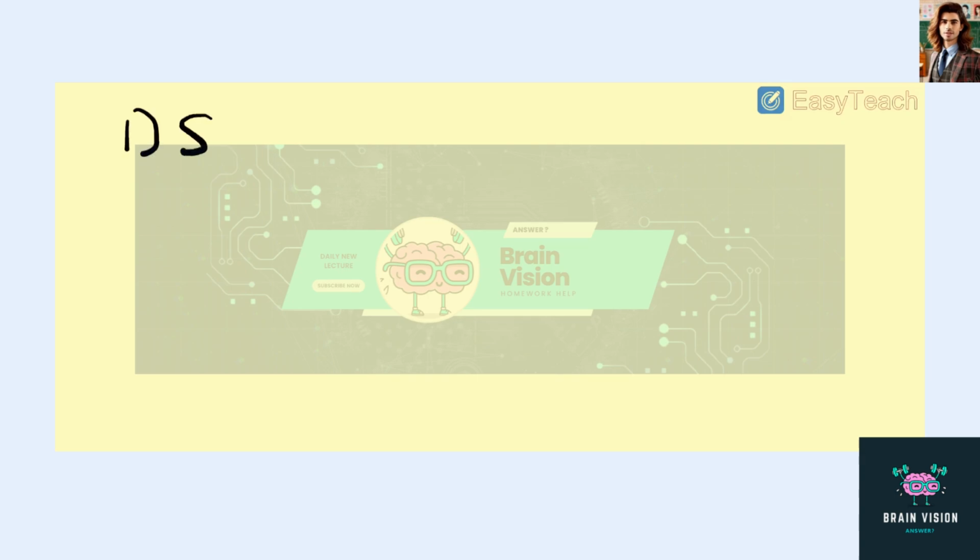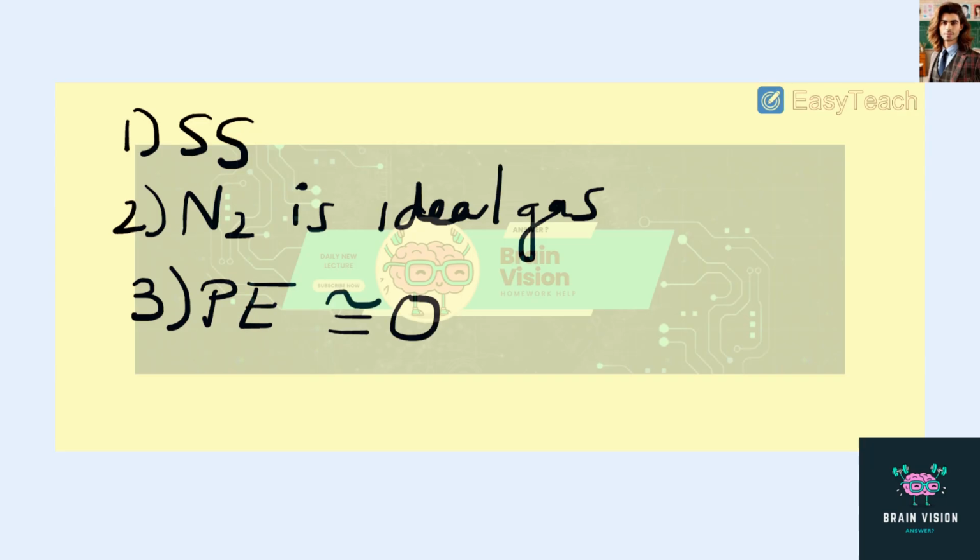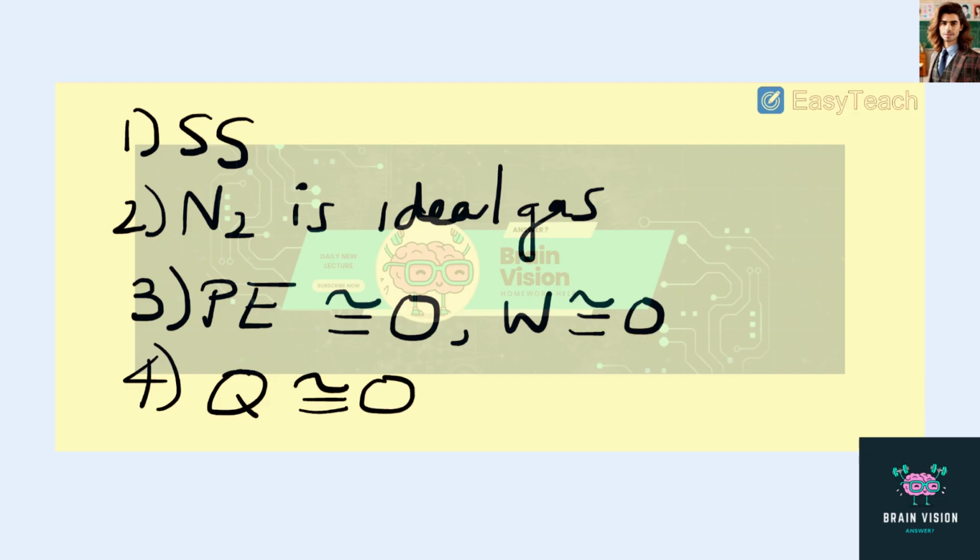So we are going to assume that this is a steady state process and that nitrogen is an ideal gas. We're also going to assume that potential energy changes are negligible, there are no work interactions, and that heat transfer is also negligible.